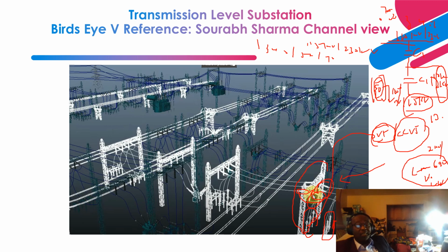These insulators are designed based on the level of voltage, the line-to-line voltage, so the number of them is based on that voltage. From here you come in, and similarly we have insulators on this side, then vertical insulators on this side. Then we have a drop-down conductor, it drops down, goes through a disconnect switch, and comes in here to energize this